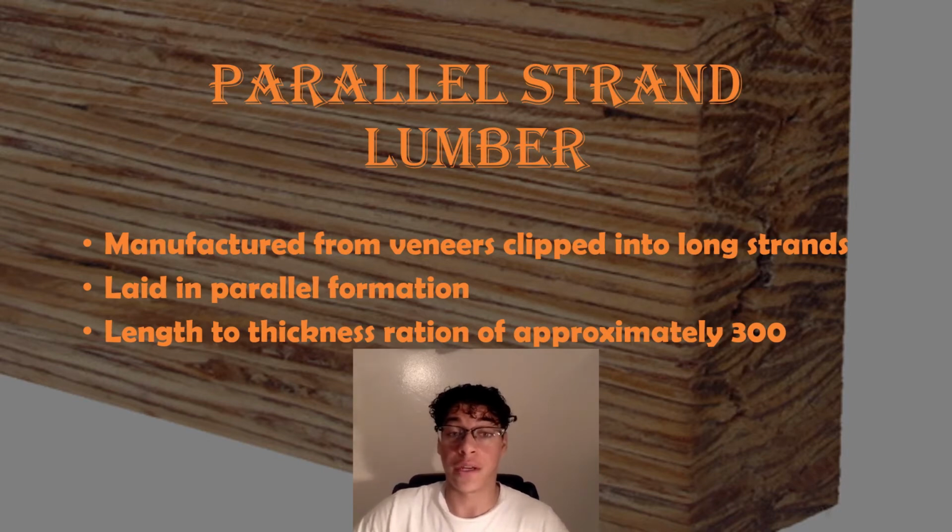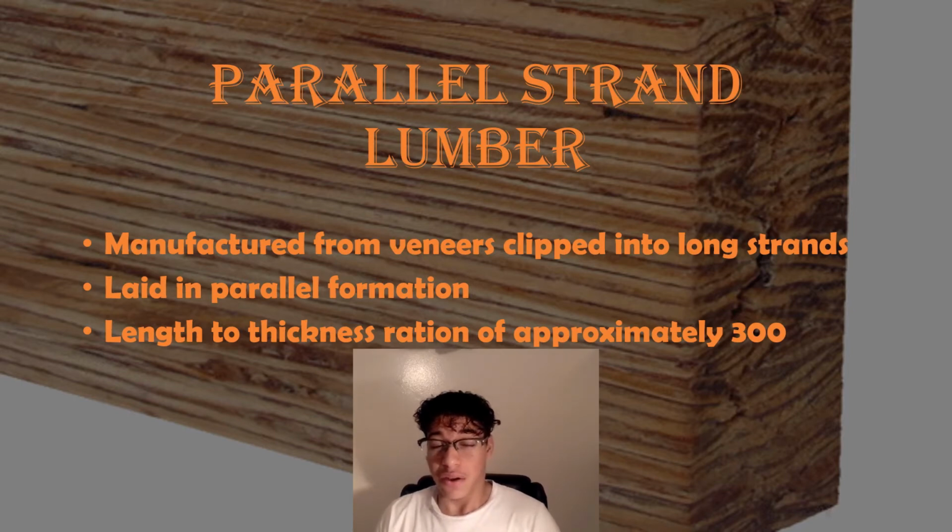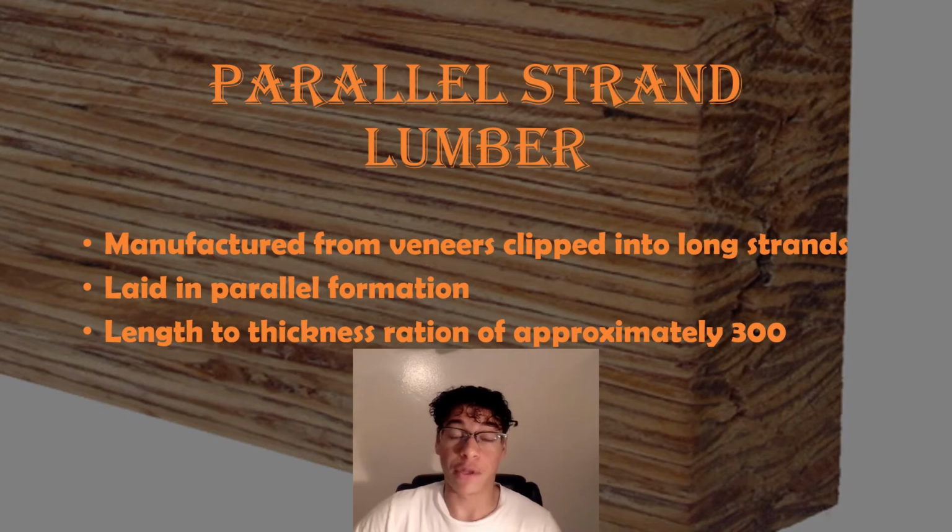Alright, so here we have the second type, which is parallel strand lumber, and it is manufactured from veneers clipped into long strands laid in parallel formation, and its length to thickness ratio is approximately 300. And parallel strand lumber is the heaviest, strongest, and most expensive of the lumber products overall. So let me show you a few examples of what they look like.